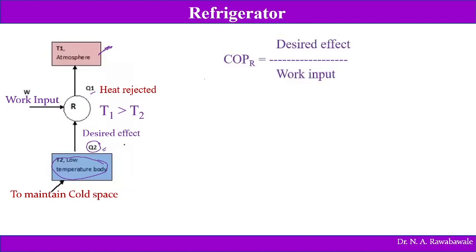Now we can see the COP of a refrigerator is defined as the ratio of desired effect to work input. So what is the desired effect? Our aim in this refrigerator is to maintain this body at a lower temperature.